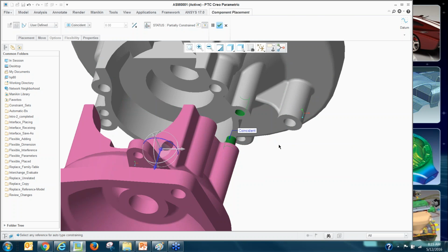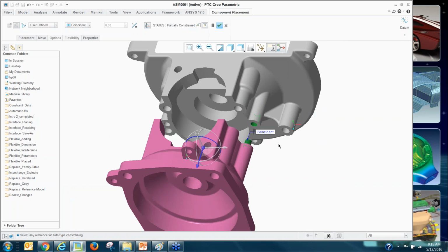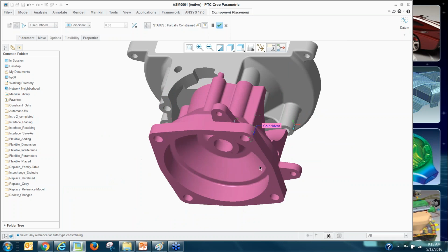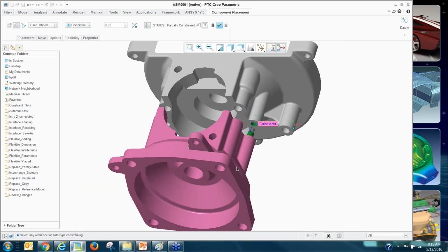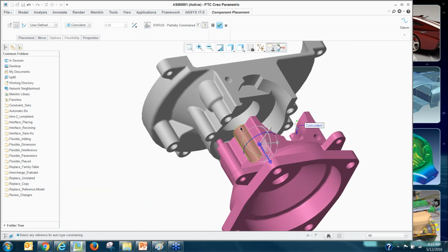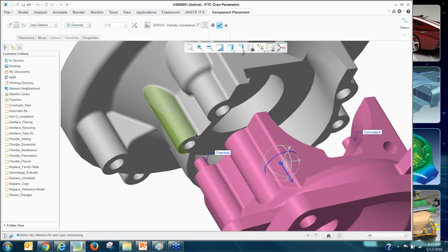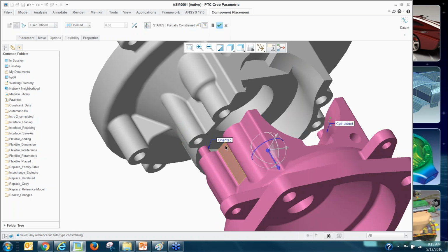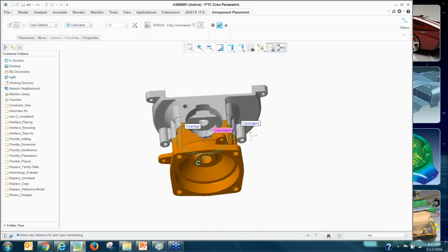And this is not new in Creo. It's been there in Wildfire 4 or 5, and it's even there in the Wildfire releases. Pretty nice tool, I thought, that I've not seen a lot of people take advantage of. And then I'm trying to test my degree of freedom. I might want to add another constraint here. There it is, right? I've fixed the orientation. Now I still have 1 degree of freedom there, right? Pretty straightforward. So I can just pick those references and I'm all set.